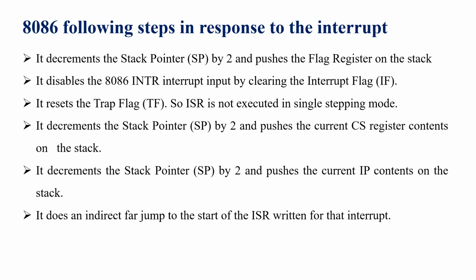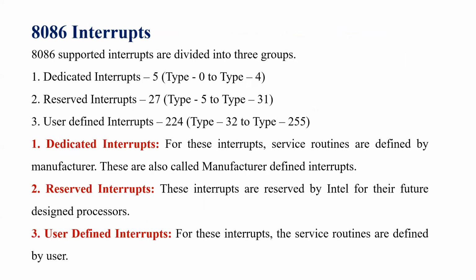Later, we have to calculate the service routine address with the help of the IVT. Then we jump to the interrupt service routine. So like this, this is the sequence of steps the 8086 should follow. Next, we'll go on through the 8086 interrupts.